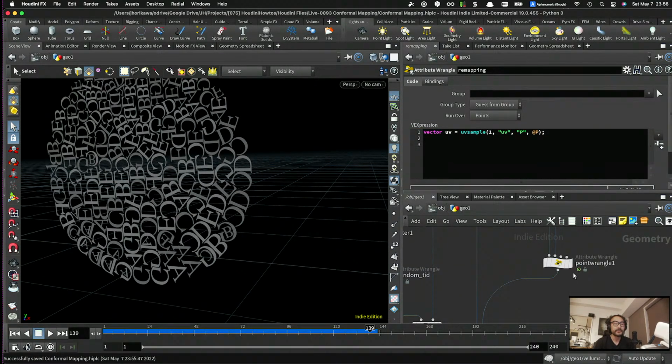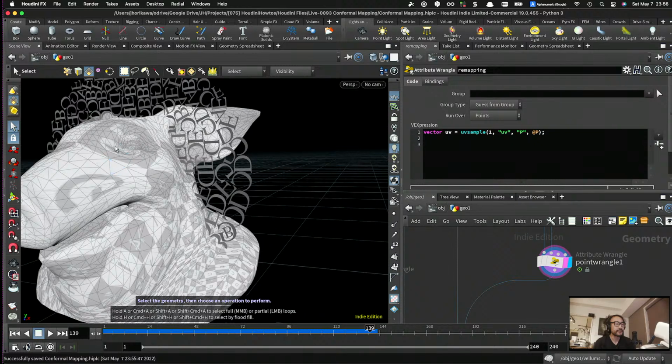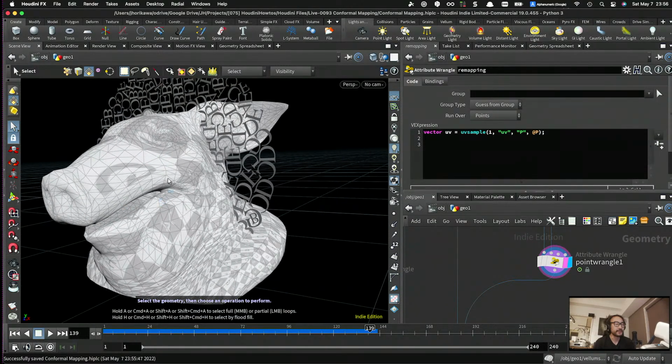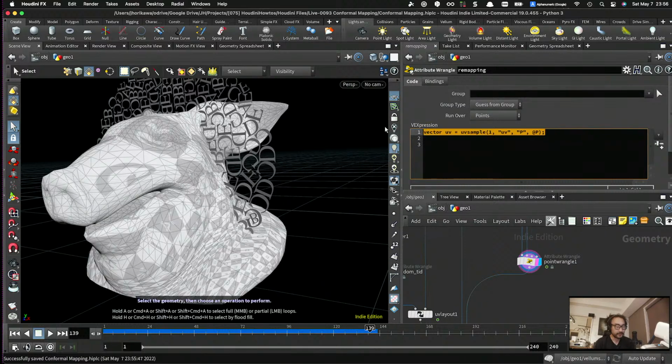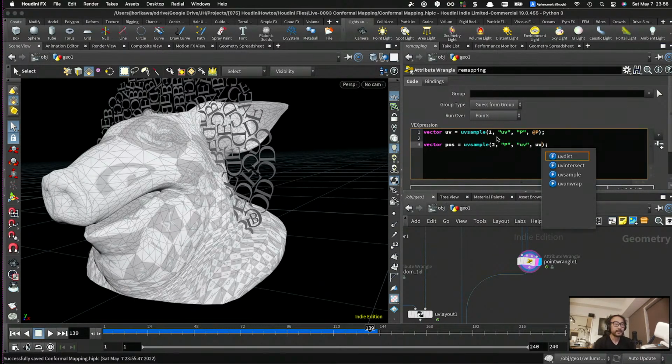Now next thing you want to do is to get the point position on top of this three-dimensional geometry using corresponding UV. So similar to what you did here, final point position you want to get is accessing to the third input. What you want to get is the point position that what you want to use as a sampling is UV, and you want to use the one that you have just got as a sampling value.